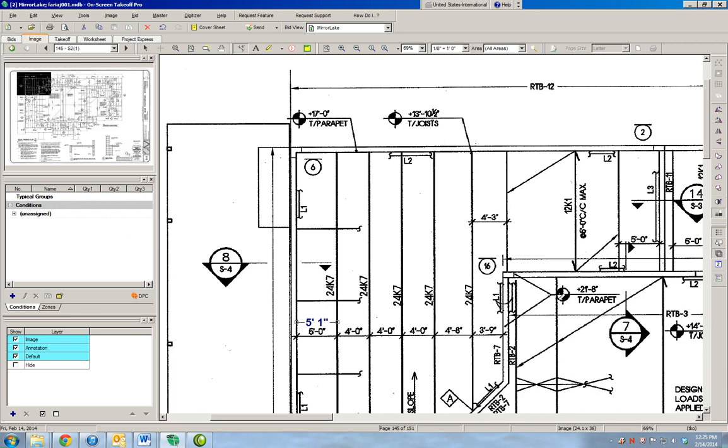So if we go back to the drawing, we see that these are 24K7, and when we look at the files, we have 24K6 and 24K10. So the 24K7 is not exactly in this table. What we could do in order to get an approximation is to go with the heaviest one, which is the 24K10.